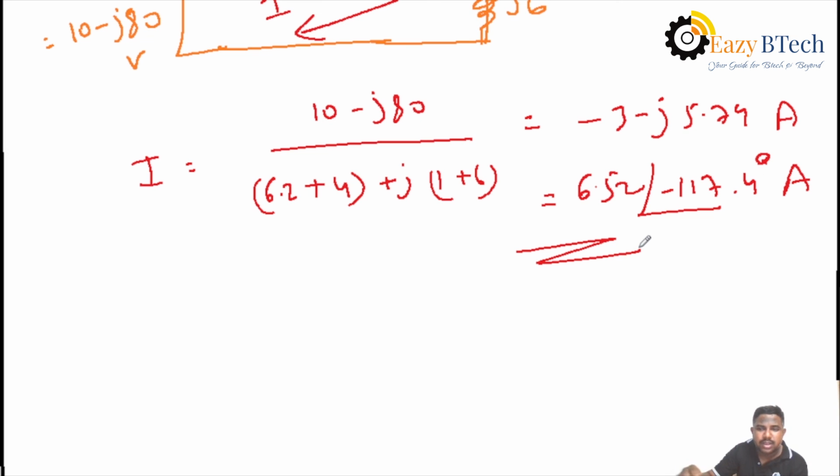Okay. In this way, you can find out the Thevenin's resistance and voltage, draw the equivalent circuit, then find out the loop current. For any given circuit, the first step is you can open the element. At that open element, you have to find out VThevenin as well as RThevenin.